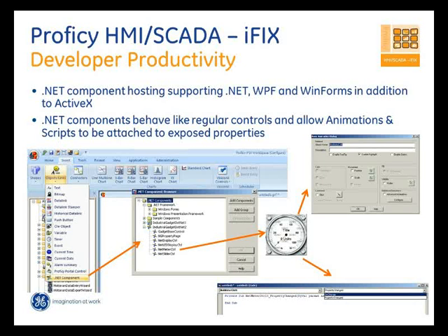So if you have used your iFix Dynamos, created a graphic, and there's a special .NET object that you have created that gives you some more efficiency information or some information related to some analysis that you have done, you can put that object next to it without having to do further work of wrapping it into an ActiveX. Now, if you have exposed any of the animations or scripts or any properties and methods as part of the development of that component, it will behave the same way as any iFix Dynamo does. So when you right click and go to animations, whatever properties are exposed will be available as part of the animation dialog, and you can interface with that object as well.